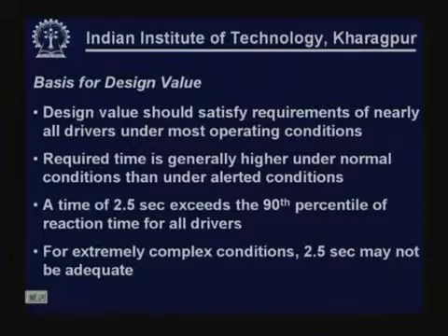Basis for design value. Design value should satisfy requirements of nearly all drivers under most operating conditions. So, nearly all drivers may not be 100%, and under most operating conditions, not under all operating conditions. If we try to select a value which will satisfy the requirement of all drivers under all operating conditions, the value will be substantially large.